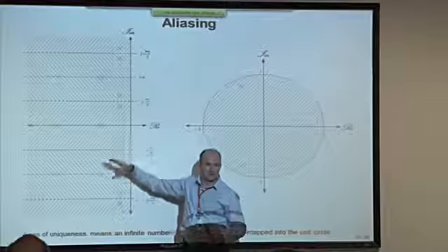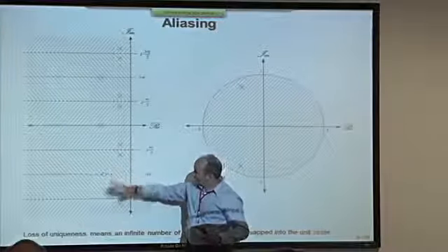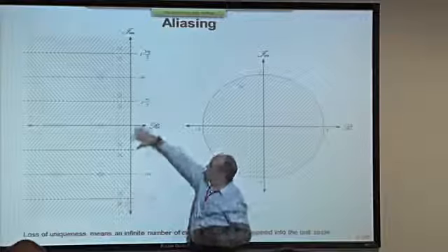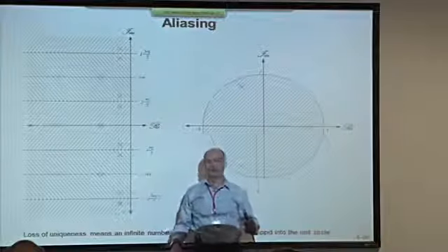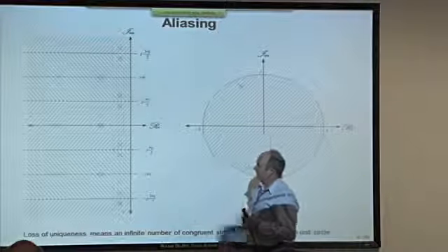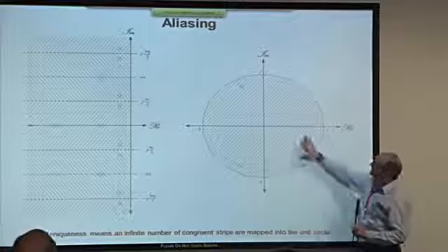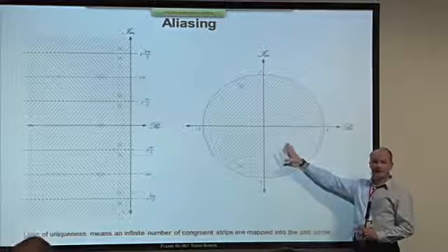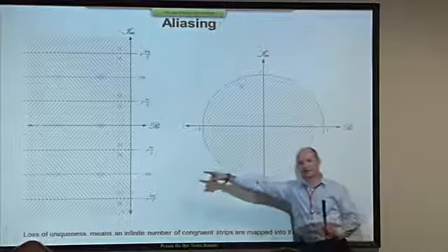And each of those strips contains another identical pattern of poles and zeros. And then that's reflected again down here and reflected up there. There are an infinite number of these other strips known as complementary strips, each containing an identical pattern of poles and zeros. And yet, in the z-plane, there is only one pattern of poles and zeros. One set over here, many over there.